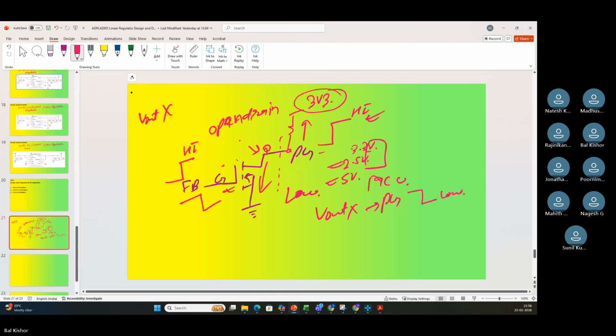Okay. When my V out is okay, just consider it is okay, more than 90%, they have programmed it. If it is okay, the FB pin will go low, making sure that MOSFET does not turn on. Okay. And if the MOSFET is not turned on, the power that is connected here, logic level to PG pin, do you see any way it will go to ground?